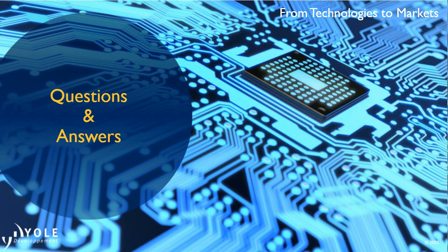For example, one of the technologies is Xperi's hybrid bonding technology, which entered the market in 2016 through Sony's CMOS image sensor in the Samsung Galaxy S7 mobile phone. So this capability to achieve interconnection with a pitch lower than 2.5 micrometers has been the key factor and the driving motivation for the industry to look into this. So with this key milestone in mind,